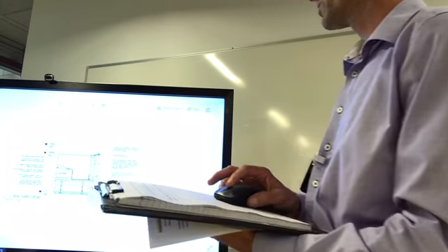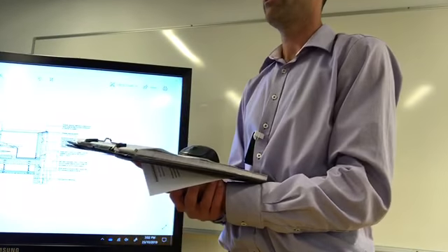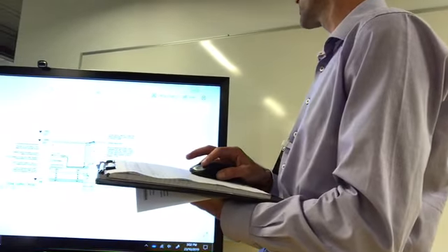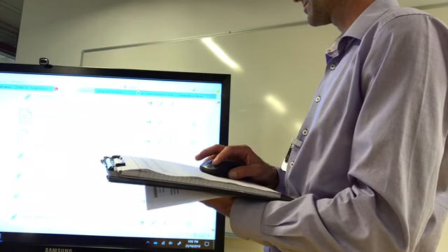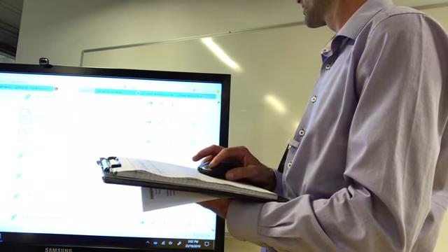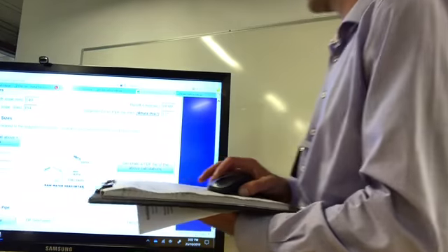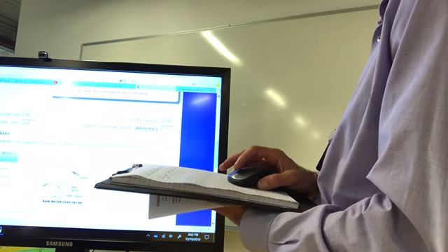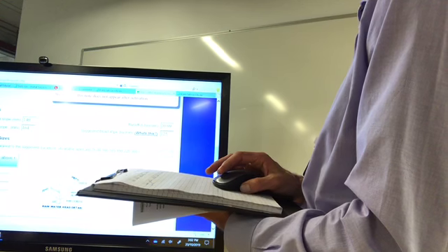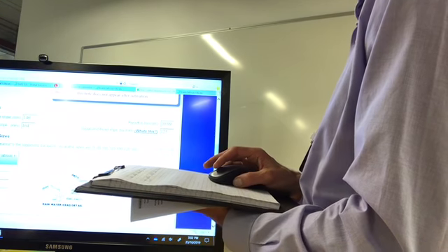Then you also want to size up your rainwater head from that as well, which is also included in that. We've determined our box gutter size, and then for the rainwater head, enter the trial downpipe size nearest to the suggested diameter above.